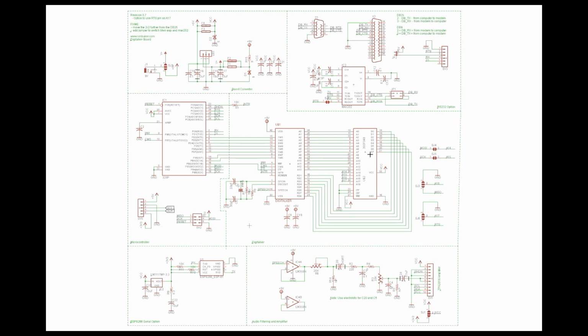In this case, I chose to use a 39SF040, which can store 512 kilobytes of data. Typical Digitalker chipset is like 16K, so you could represent many sets of words in this. And as you can see, I broke out the extra pins, total of 4 of them broken out, with paths to connect them to the microcontroller.